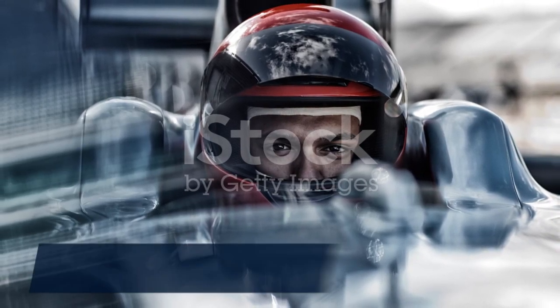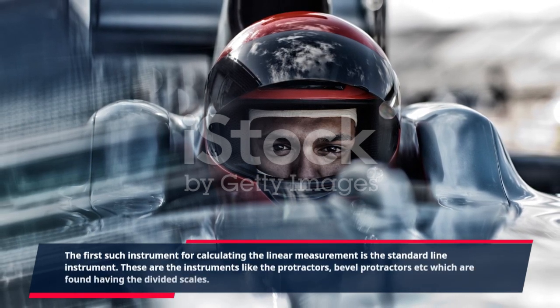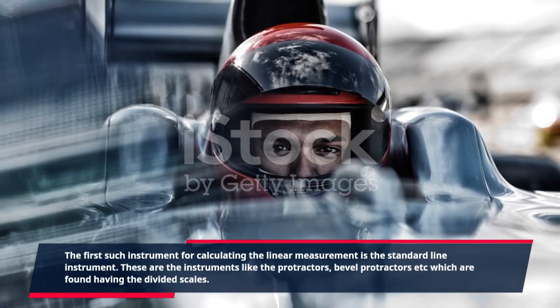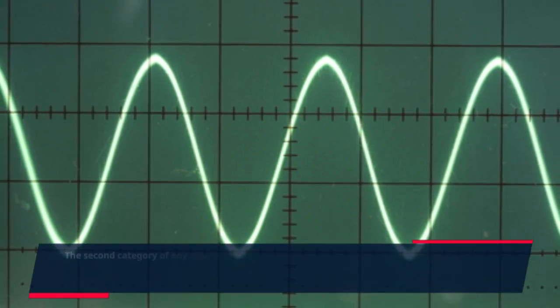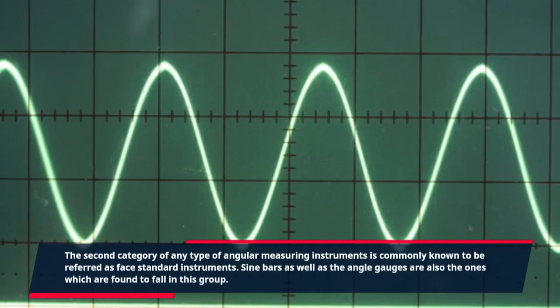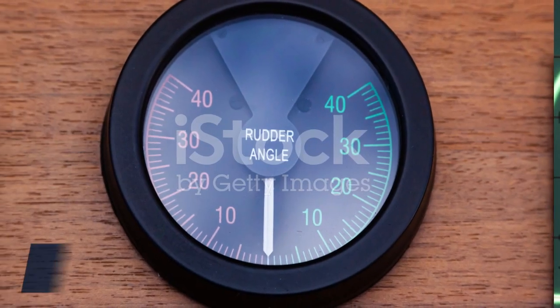The first such category of angular measuring instruments is the standard line instrument. These are instruments like protractors, bevel protractors etc., which have divided scales. The second category of angular measuring instruments is commonly referred to as face standard instruments. Sine bars as well as angle gauges also fall in this group.